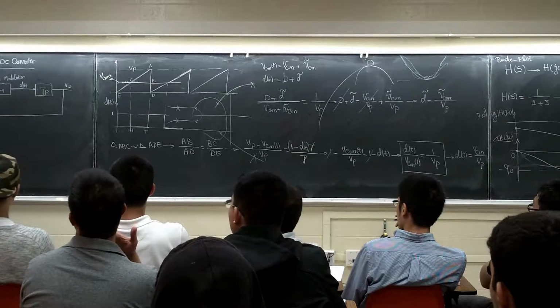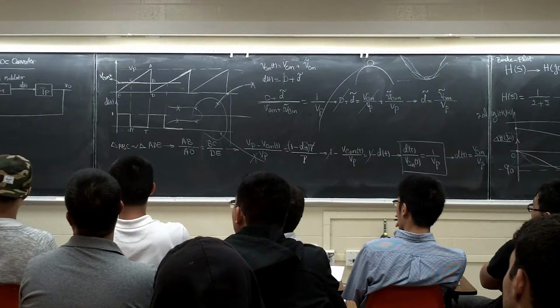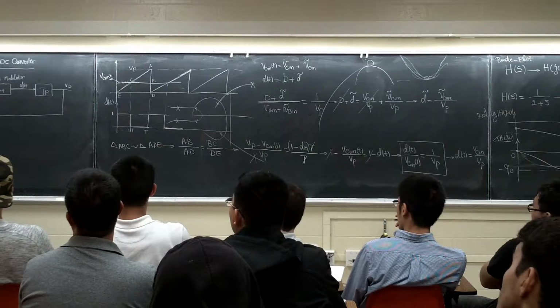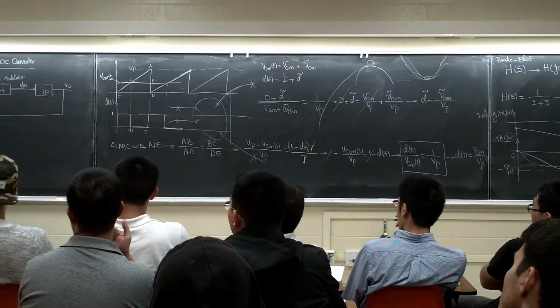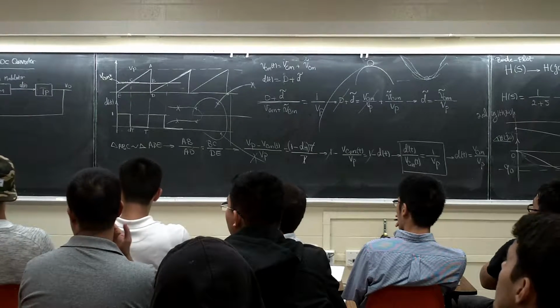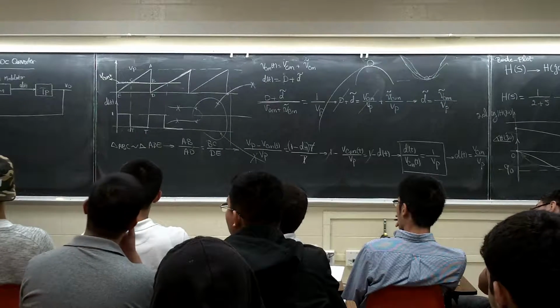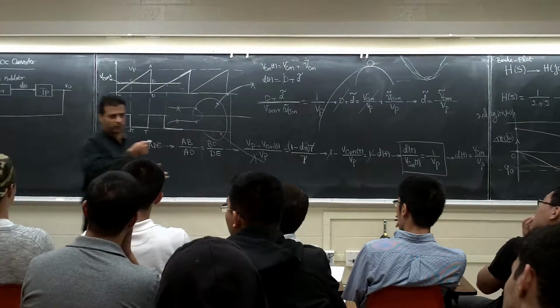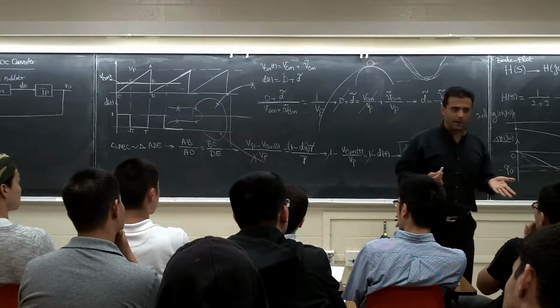Just magnitude. Once you are there, use the scope to zoom in on the voltage waveform. You put, for example, 10 volt. Go look at it, it's not 10 volt. There's going to be something around 10 volt. Always there is an error. But if that error is 1%, based on the application, maybe it's perfect. Now, for what you're doing in the lab, 1% is perfect. If you have a 10 volt, and now 1% is how much?